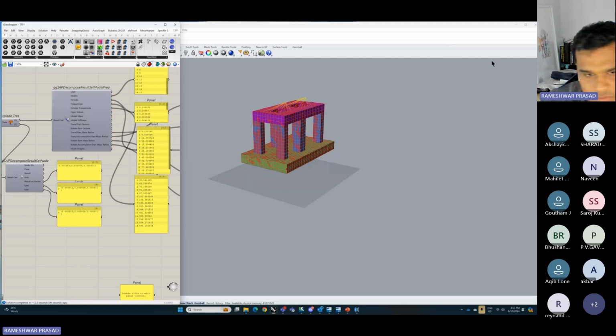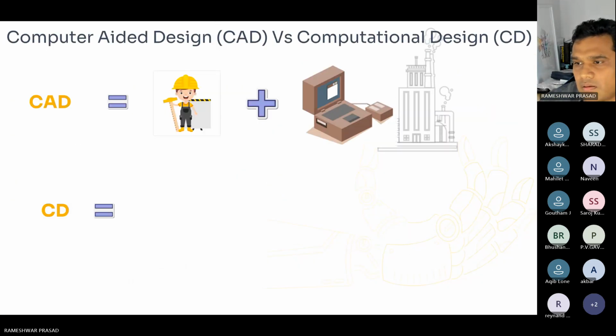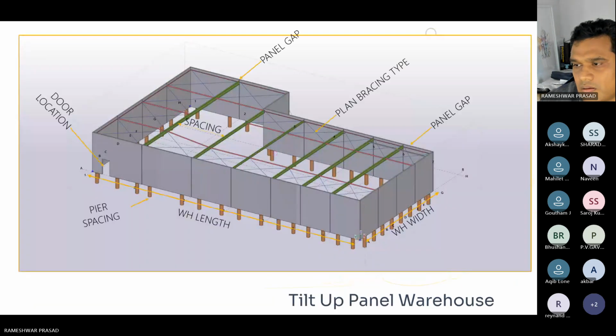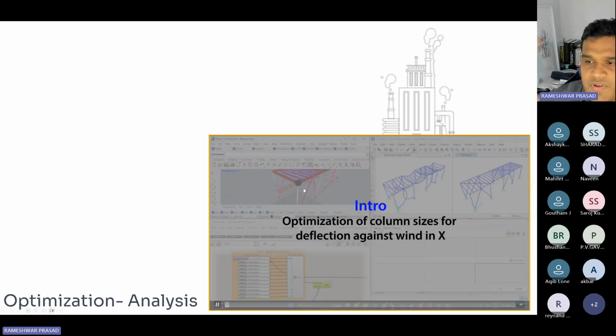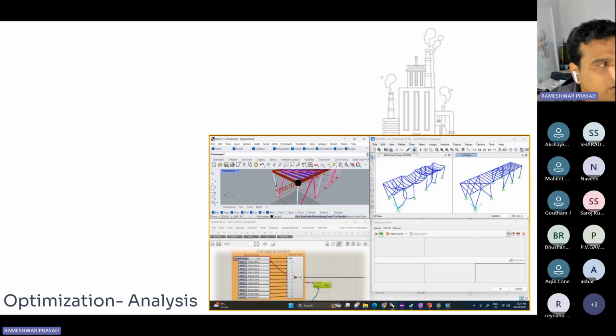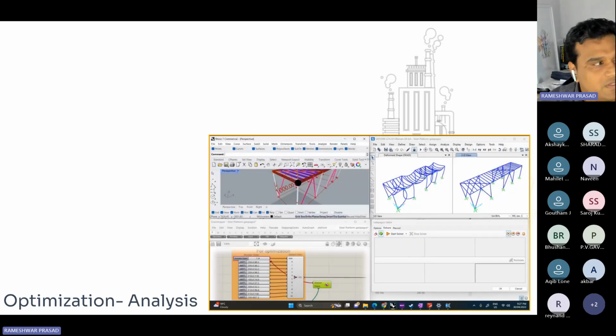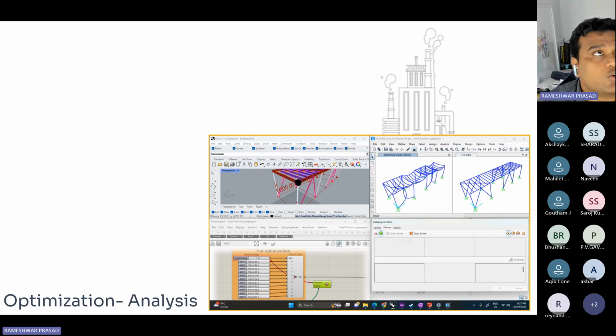Right. So you remember the video that I showed you during the presentation? Let me just bring it back. Say, for example, you start with the process of modeling your structure in Rhino and Grasshopper, right? I'm assuming that you must be using ETABS to perform performance-based design, or Perform 3D. I don't know whether Perform 3D has API access, but you definitely have geometry engine plugins that export to ETABS. So you set up your model in that fashion, and then you put in an algorithmic logic that basically imports the deflection or the drift, whatever it is, for a particular level or a node back